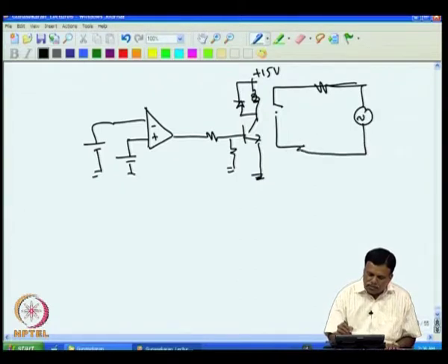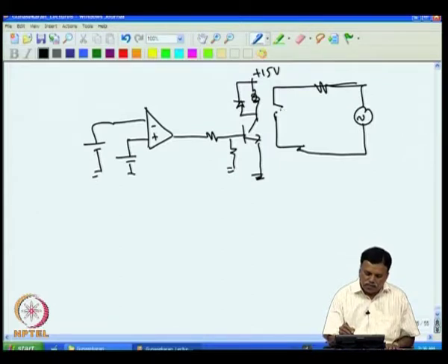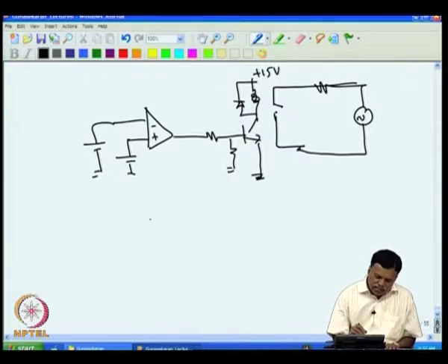But as we said, the relay is a mechanical object. Whenever contact is made and broken, some part of the metal is lost, and the number of times it can be operated gets reduced. So, for very frequent on-off switching this is not suitable, but it can operate either AC or DC, and high power can be used. Suppose you have a DC of high voltage, then the on-off controller also can be used like this.